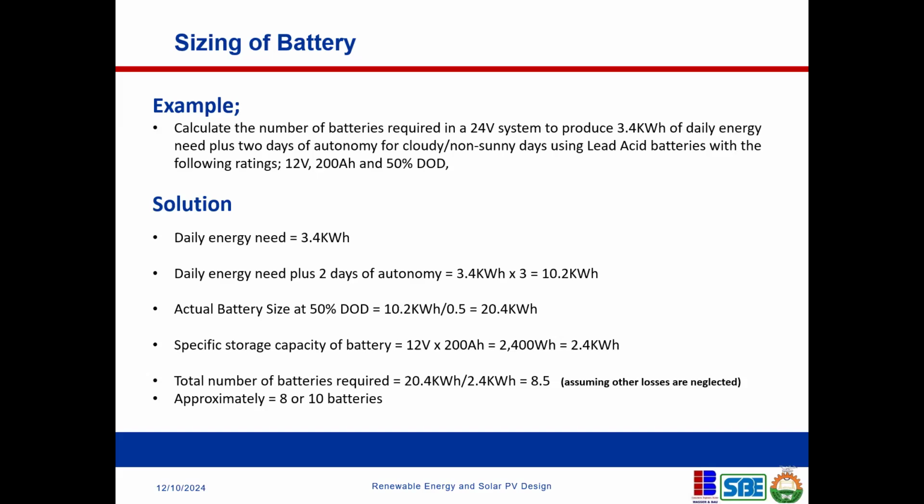I want us to be clear on this. And when you're looking at your inverter, make sure you have the right size of inverter that can take that voltage. Otherwise, you blow up the system or your system will not work. Now, when you get an inverter, look at the input voltage and make sure your battery voltage corresponds to the input voltage of that inverter.